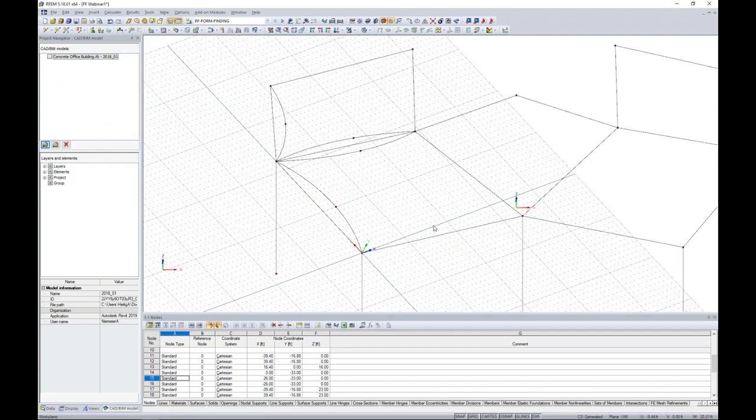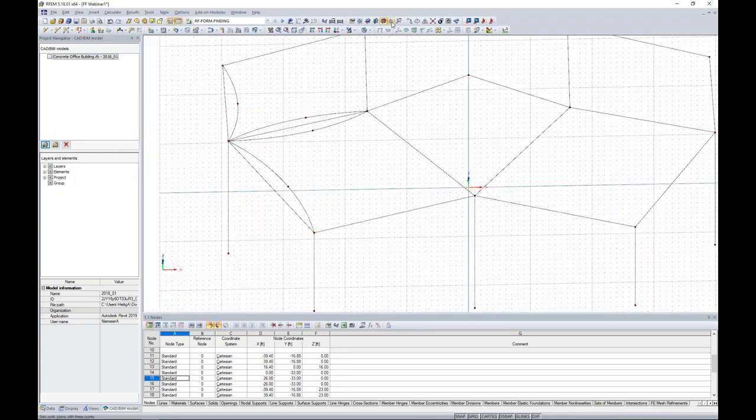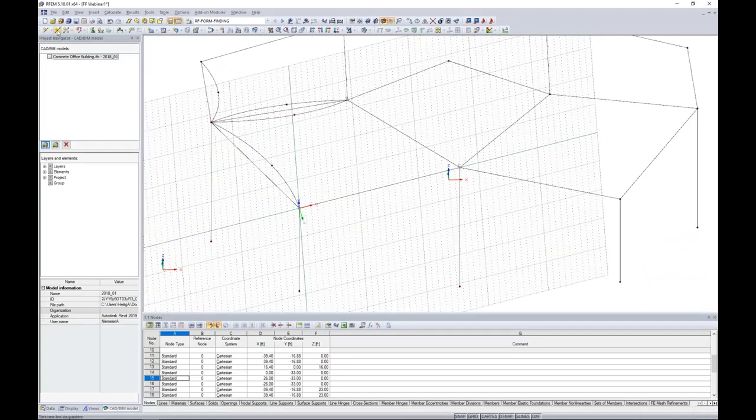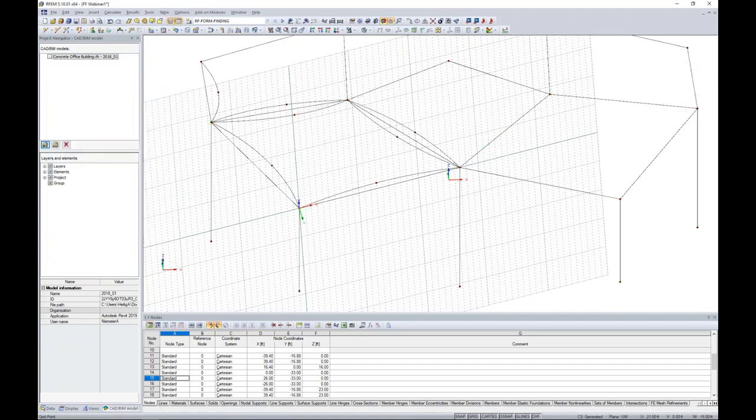We need to lastly do so over here. So we click this option up in our toolbar for a user-defined grid, click our 3 new points, and now we have the specified angle. We go back to draw a new line element as an arc with 3 nodes and continue on with this process for our additional cable elements. And one more time for our 3rd cell.